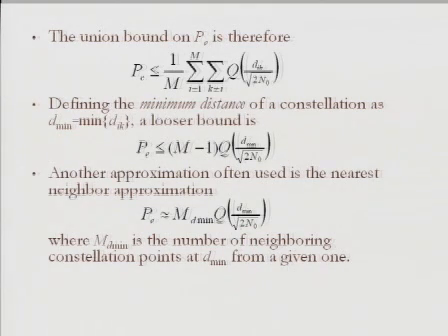So once again, we're finding these familiar Q functions that we already saw earlier in the course. Remember that in chapter 2, when we dealt with shadow fading, we also found Q functions, because the shadow fading was log-normal. So when we express things in dB, it was Gaussian in dB, and so we found Q functions. And here we have that the noise is Gaussian, and so when we express things in linear scale, we again run into Q functions everywhere. So this is the union bound expression.